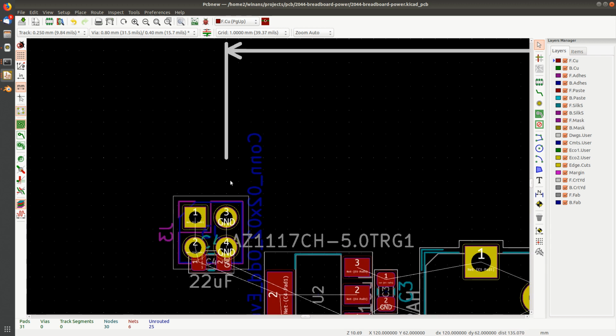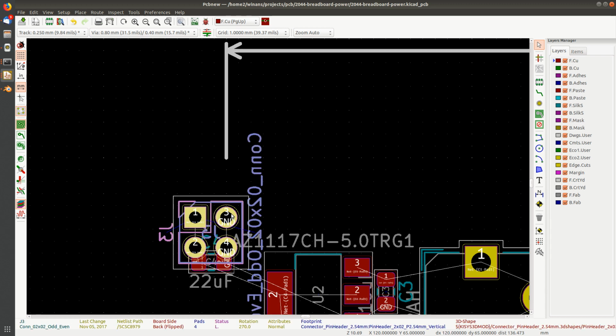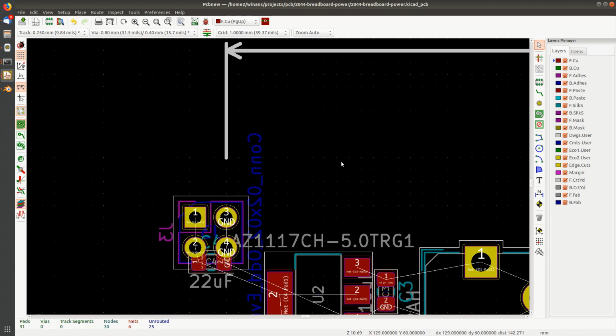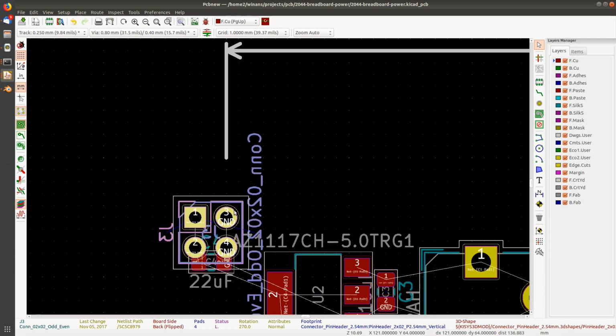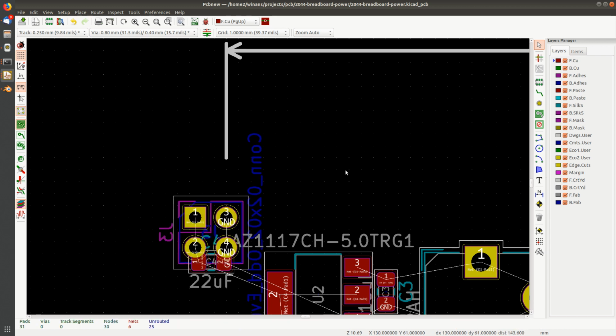So in addition to the snap to grid, it does give you one extra point, which is to keep it aligned in this axis. It probably does it in the other one as well. But even so, what I'm going to do is grab the pin that I want to move it on. Now it's forcing me to grab the whole one, all right? I suspect that it's doing that because it's on the bottom of the PC board and I'm currently editing the front, right? Let's go to the back. Now let's try to grab it.